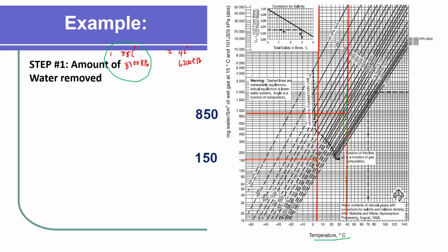Okay, all the way. Then I'm going to look at how much the pressure is. It's 8300 kilopascal. So I have 8000 here, and I have the 10,000 here. So 83 will be somehow close to the 8000, a little bit below the 8000 curve. So I'm going to draw an estimation, another line close to it, and I'm going to predict that it's going to be between 8000 and 10,000.